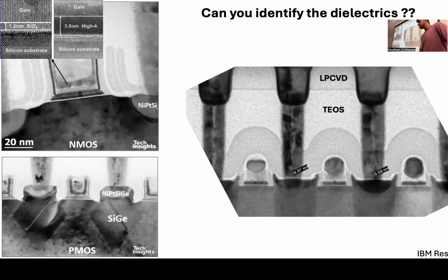But say you want to make sure that it fails only 10 years later. You can't do it at E0 because you can't wait 10 years. So typically you do it at much higher field and much higher temperature. Because it usually follows some kind of Arrhenius relationship for the time to failure, you can do it at a higher temperature and then extrapolate how the failure would be at a lower temperature as well as field. That's how they calculate indirectly what the mean time to failure is. You do this accelerated test.